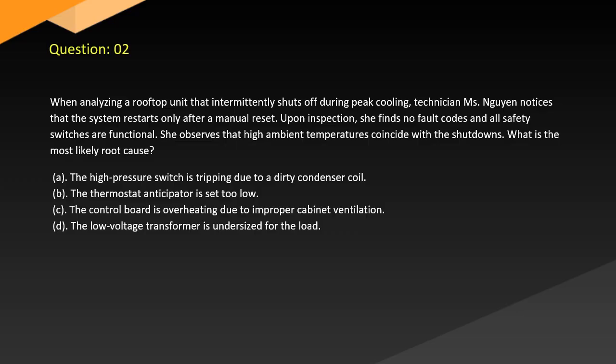A. The high pressure switch is tripping due to a dirty condenser coil. B. The thermostat anticipator is set too low. C. The control board is overheating due to improper cabinet ventilation. D. The low voltage transformer is undersized for the load.